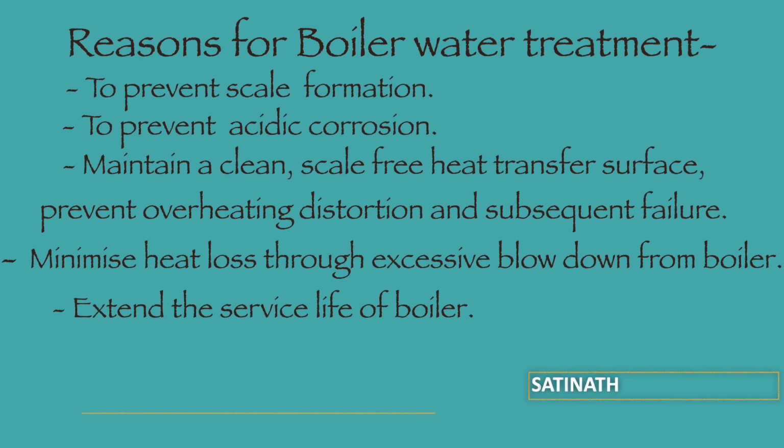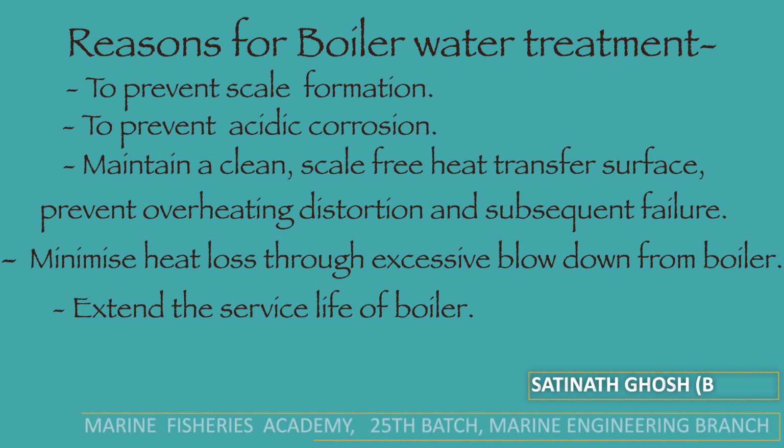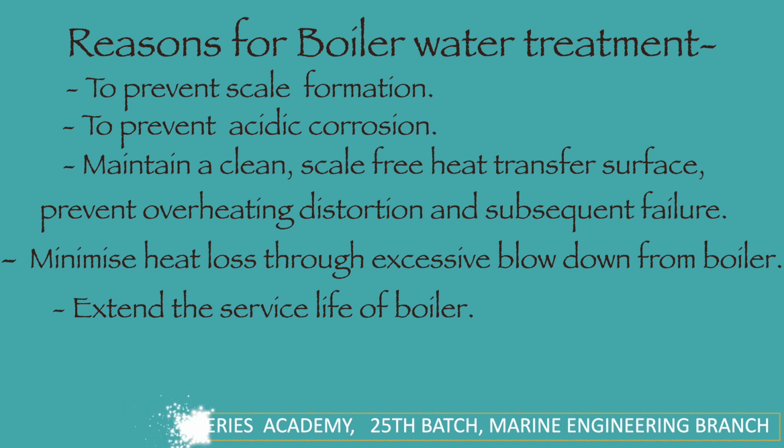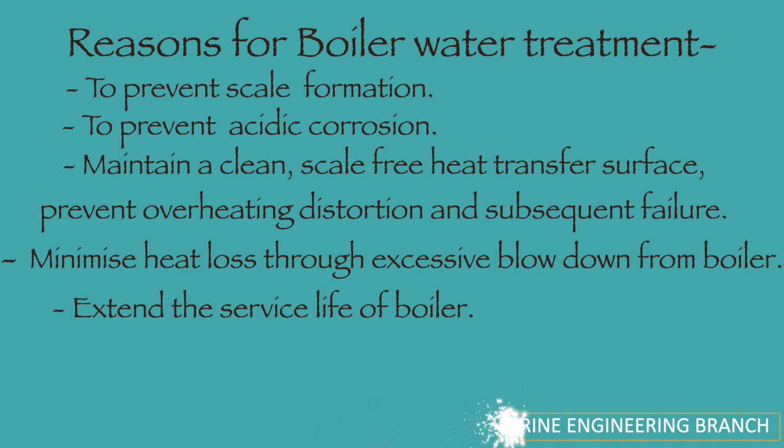Reasons for boiler water treatment: to prevent scale formation, to prevent acidic corrosion, to maintain a clean, scale-free heat transfer surface, to prevent overheating, distortion and subsequent failure, to minimize heat loss through excessive blowdown from the boiler, and to extend the service life of the boiler.